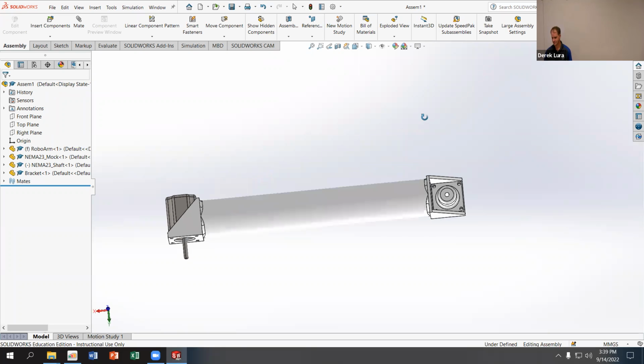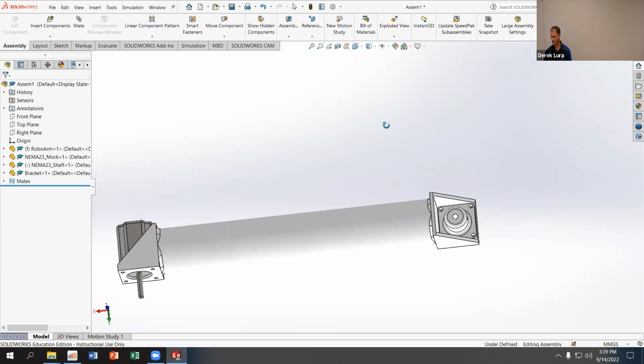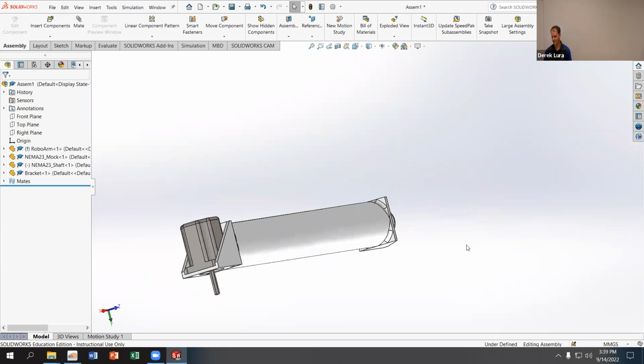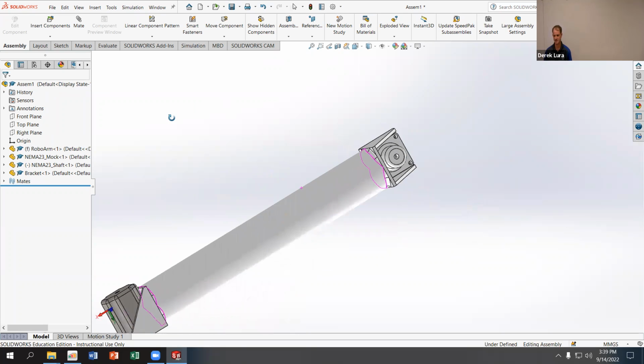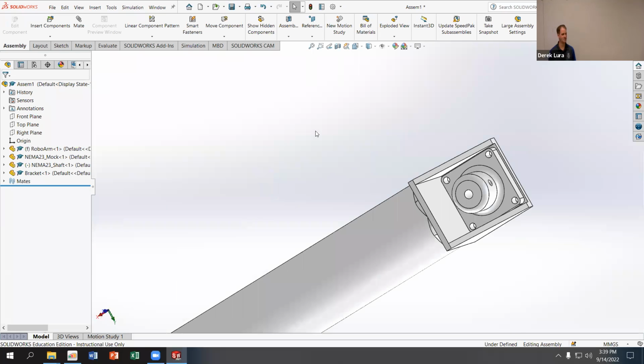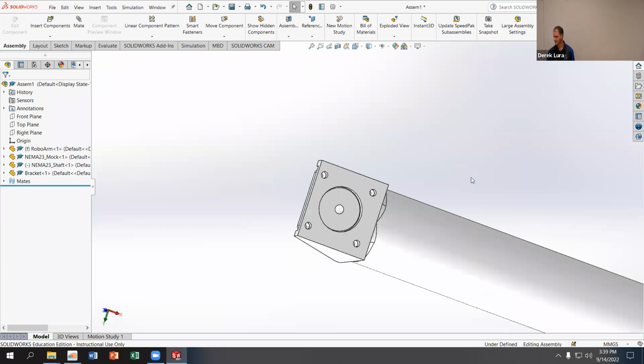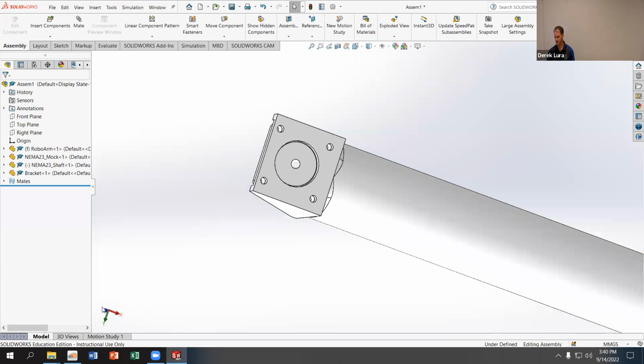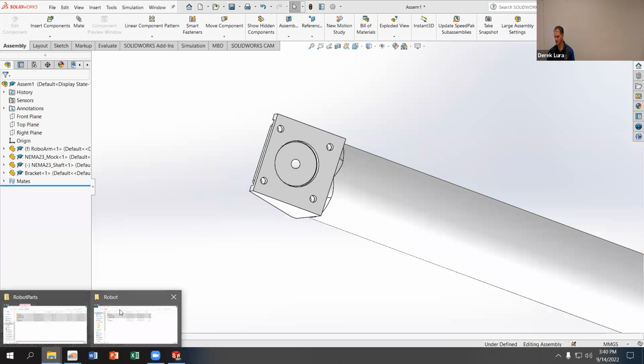All right. The next thing that I want to do is add the pins in all of these positions. And one of the things you can do in an assembly to make things faster is use what's called the copy with mates tool inside the assembly. So I'm going to add one pin, define the mates for that pin, and then I'm just going to copy it and reassign the mates for all the different positions. And if I remember correctly, I think there's a hotkey that I can actually do multiple at the same time.